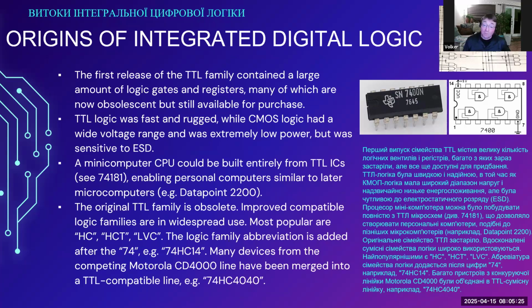The original TTL family is obsolete. I had mentioned that the high-speed CMOS and the low-voltage CMOS series are the most popular at the moment. They are newer families. They might take over at some point in time. But at the moment, if you're looking for a TTL compatible circuit that is supposed to be connected to a microcontroller, you most likely will be choosing a high-speed CMOS chip or an LVC chip. I think I'd mentioned that before.